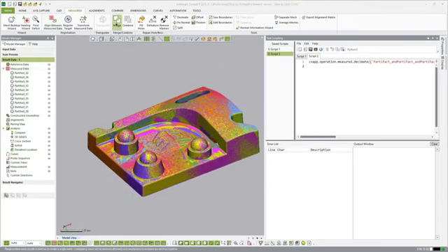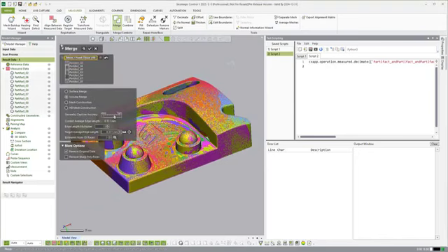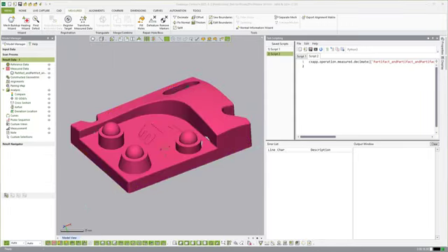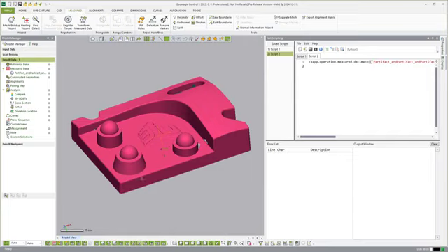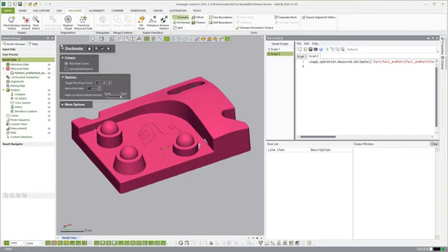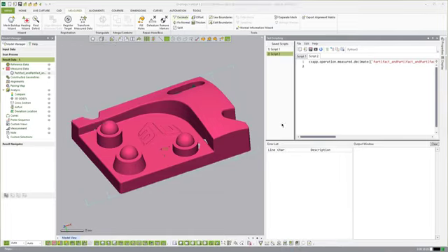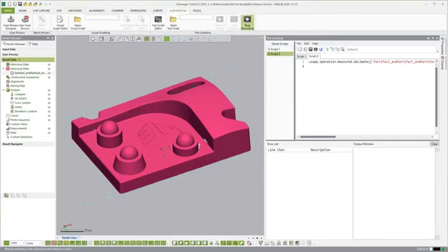And the next step is to come over to merge, and we'll just go ahead and run a volume merge. One click back from the top there. And I'm going to leave remove original data just for simplicity's sake in this script. And then we'll hit OK. So now we have one merged scan. So now let's go ahead and run decimate. So we'll say I want to decimate 25% there. And then hit OK.